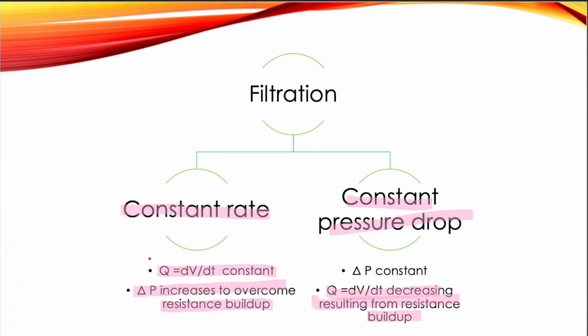So here we're going to have a cake, so we need an extra pressure so that the particles can pass through this filter, because the cake builds up at the surface of the filter. If you don't have that extra force, then the rate of the fluid feed passing through the filter will be decreasing here.